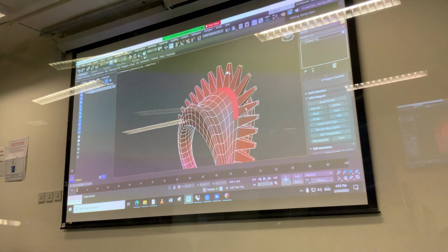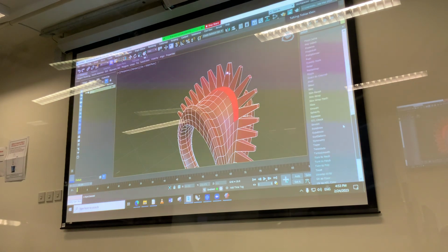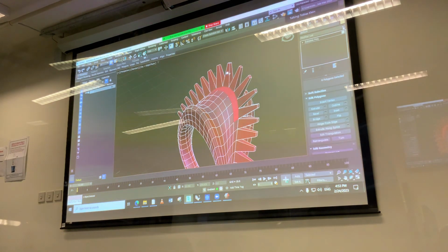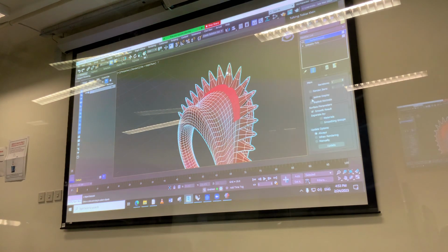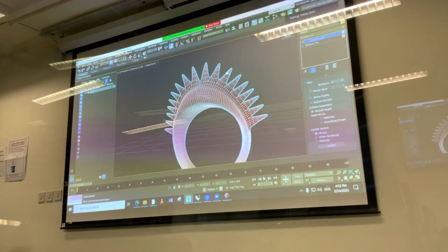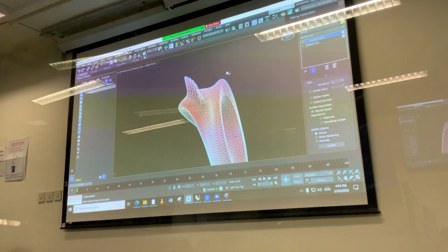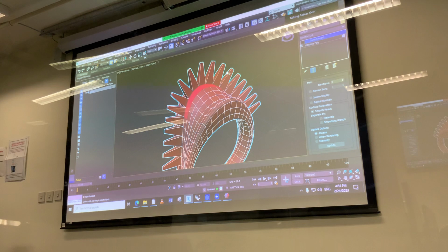And one of the things that you might want to check out is you can put a smoothing command on top of this. So that's in 3D Max, it's called a turbo smooth on the side here. Turbo smooth. And that basically shows you how this would look if you smooth it twice. So that's subdivision modeling. So now you're getting into this organic shape already. And you can switch this on or off just with making the eye on or off.